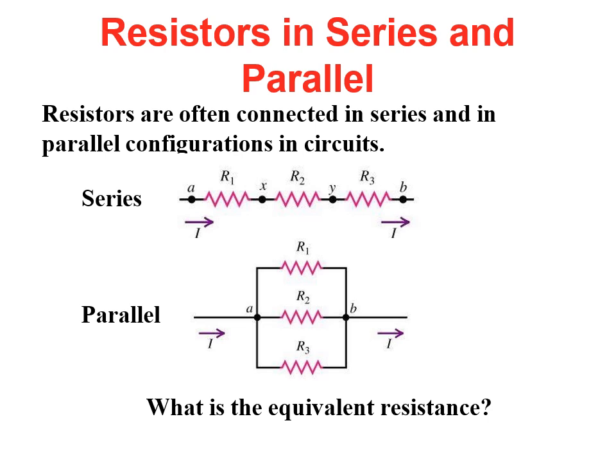If you have two resistors, for example, remember a resistor does not have polarity. It has two terminals, but you can connect it either way. There's no positive or negative side. Now, if these two resistors are connected only on one side, they are touching only at one point, and there's no path for the current to divide, then those two resistors are said to be in series.